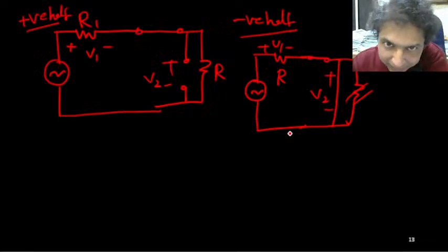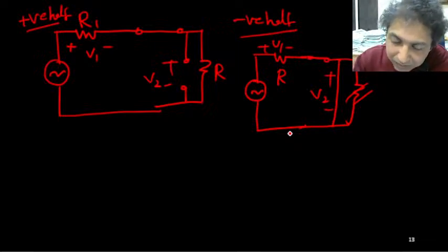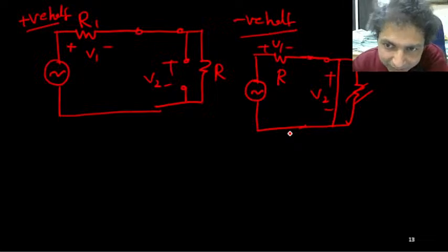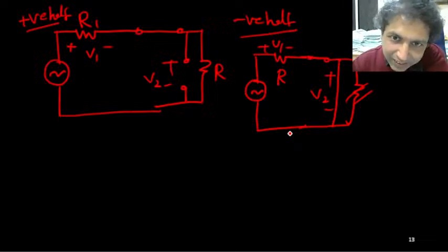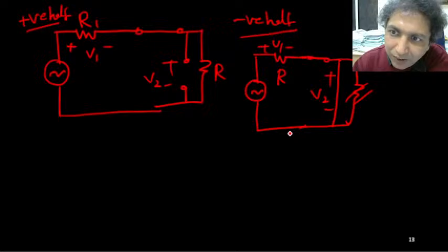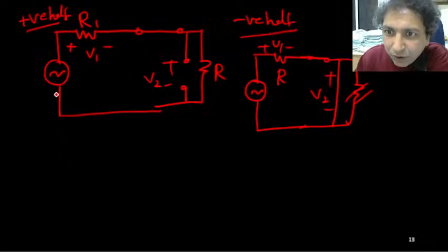Yes, that is the thing. The first two diodes, they are connected in parallel. It is given in the connection. So remember, one diode is always on, thus it is short circuited, no matter positive or negative half. But D3 will be on only for the negative half, and it is off for the positive half. So now can we draw the voltage?